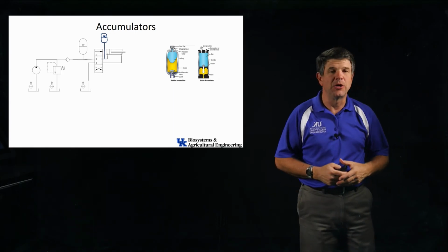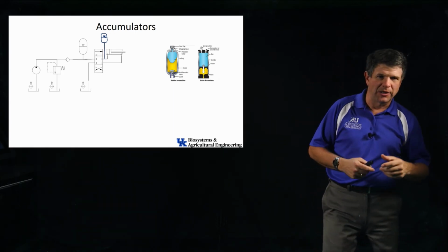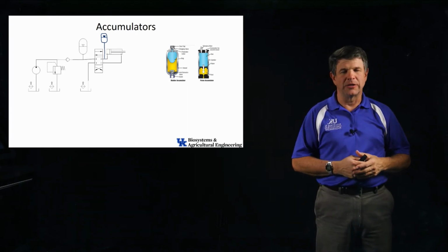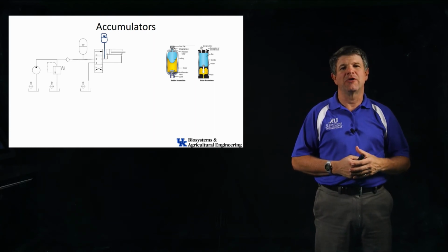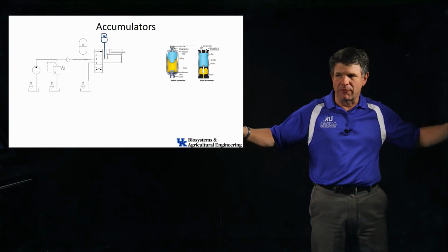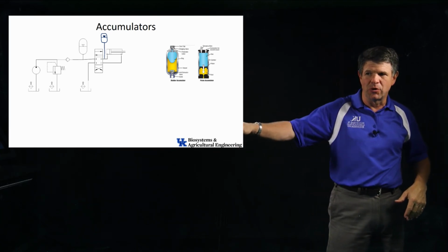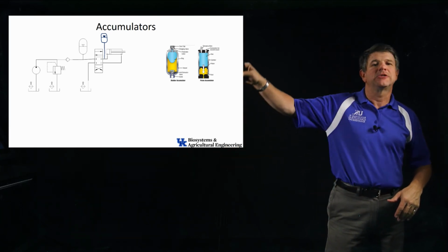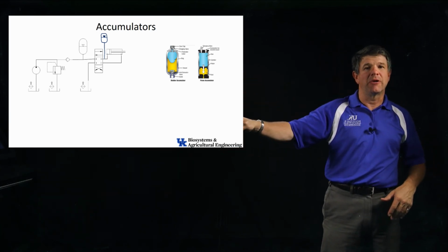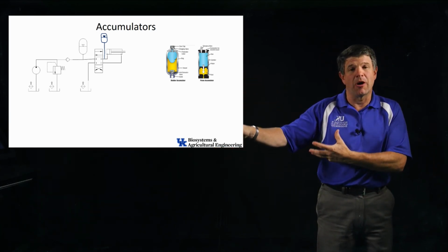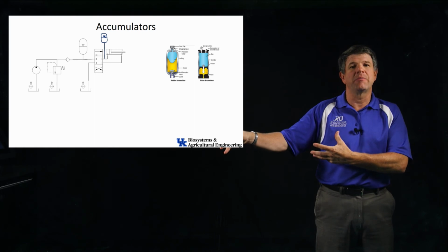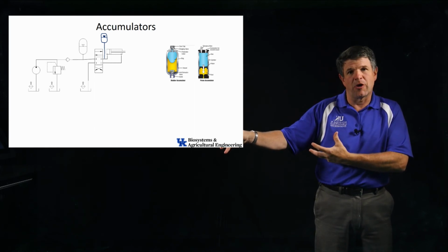And I've seen these used, and again, some of my experience on sabbatical with the major equipment manufacturers, big sprayers that have really, really long booms. You know, they're 120 foot long, so we have a 60-foot boom that's cantilevered out there, and we start hitting bumps, and this thing's bouncing around. Well, it's tearing the mechanism apart because of all those vibration loads and impact loads on the structural framework part of that machine.